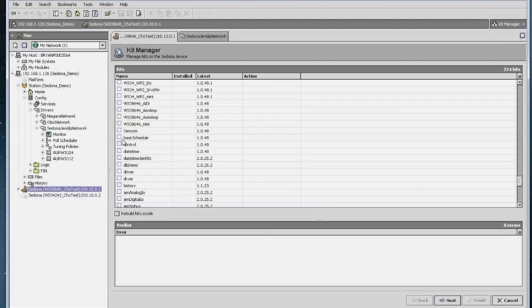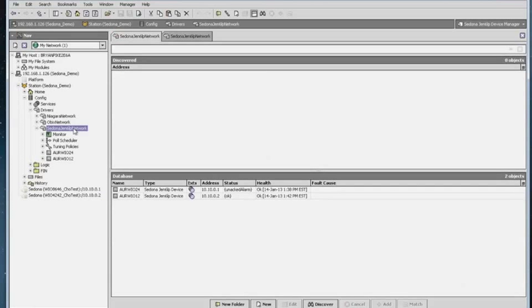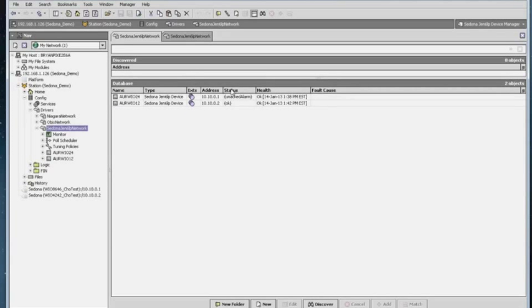build your custom logic. One thing that was added in the new devices in 5148 modules, which are installed on the 12 and the 24, is now you're able to utilize the full control kit because the memory has increased by over 500%. So literally there is no limitation in building custom logic in these devices. All logic does reside in the device itself, so it is a programmable device that does not require dependency on the JACE for communication, just to run the control sequence. All right, so we've covered the basics of setting up a network and how to tunnel. Let's bring on some more devices so you can see how additional devices join the network.